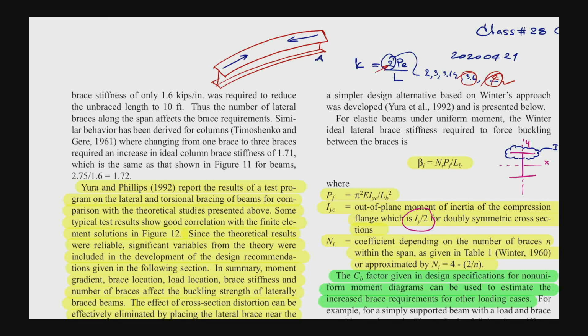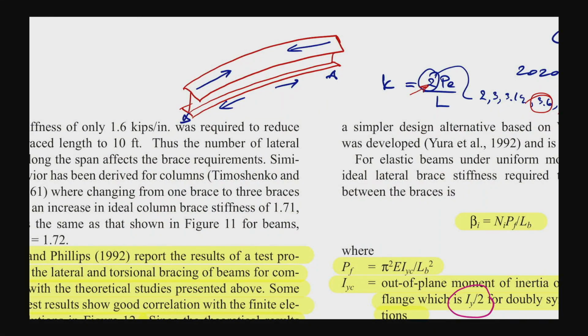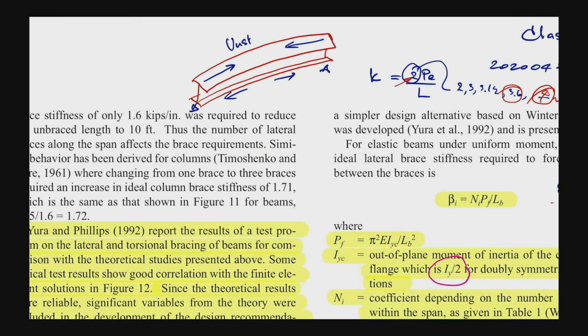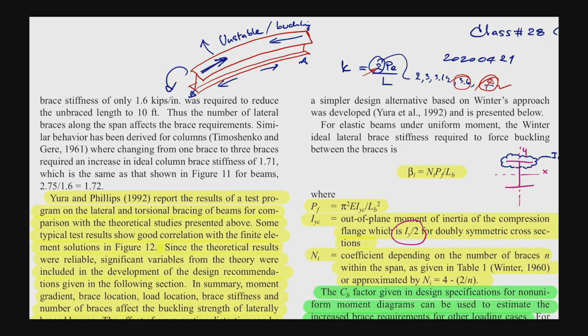But if we think of the simply supported beam like this, the top flange here is under compression, whereas the bottom one is under tension. So the part which is under compression is the part that becomes unstable. Instability is in the top flange. So that means buckling is there. So as we know, under compression the top flange buckles, and when it buckles, it goes laterally, and the bottom does not go like the top flange, so it causes torsion at the same time. So that's why we have the lateral torsional buckling in the beam problem.